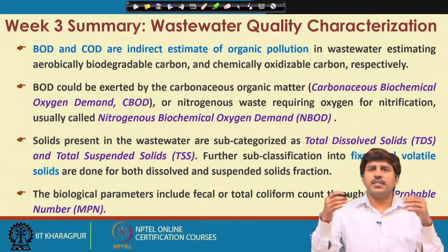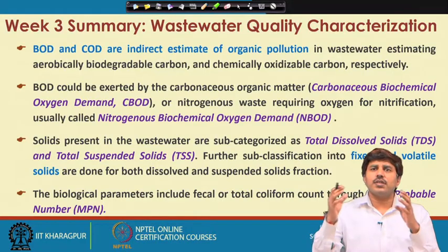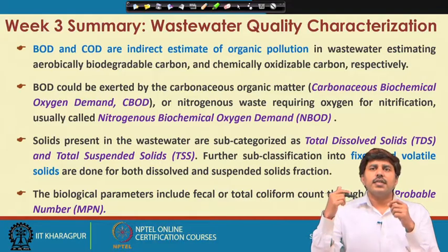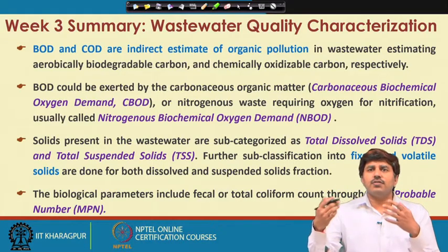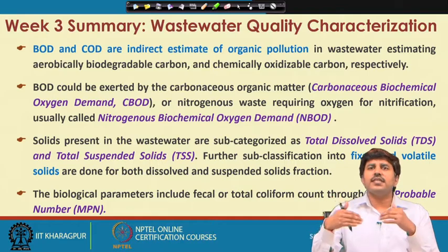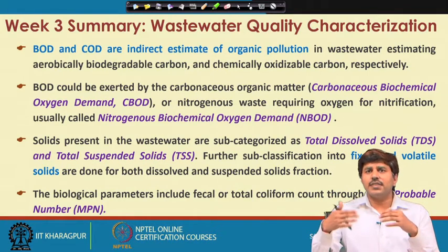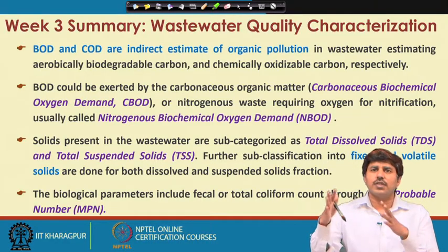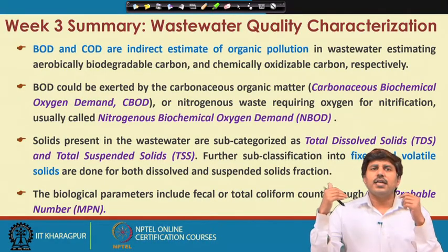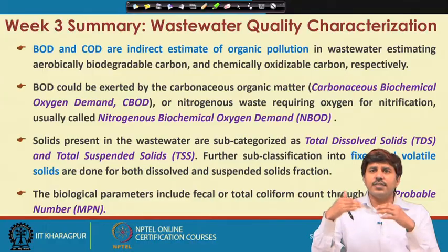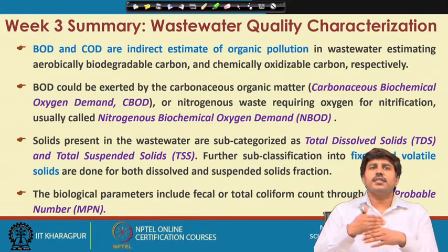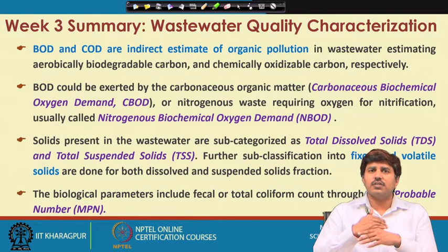Then there could be various solids present in the wastewater. We discussed that the total solids present in the wastewater are referred to as total solids, TS. Then we can subclassify them in various ways. If we filter that water, the filtrate will contain the dissolved part of the solid, so we call that total dissolved solids, and the retained mass on the filter is the suspended part of the solid, so we call that total suspended solids.